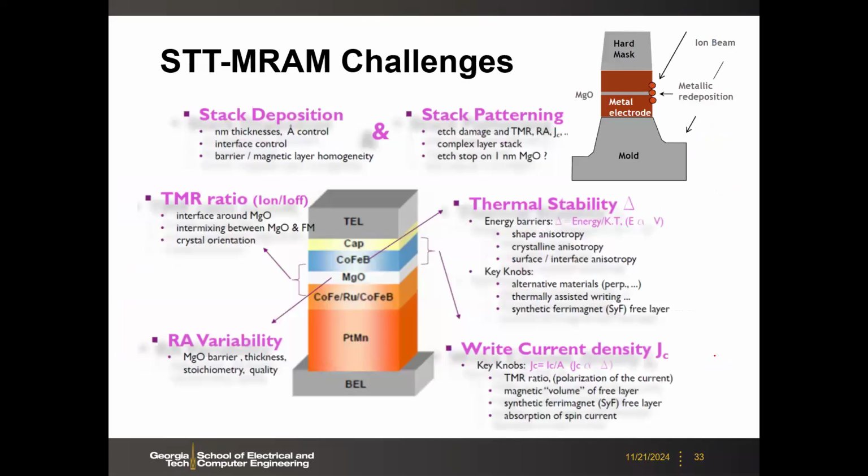So anyway, now industry switched to the perpendicular MTJ, and there are many challenges still there. I skip the details. But one of the challenges in real fabrication, if you want to scale the technology, is that when you etch the structure, the sidewall is a weak spot. Many leakage paths and defects come from the sidewall when you etch the entire stack, because you deposit those films, but you need to make isolated cells. So you etch, and once you etch, this edge becomes a weak point.